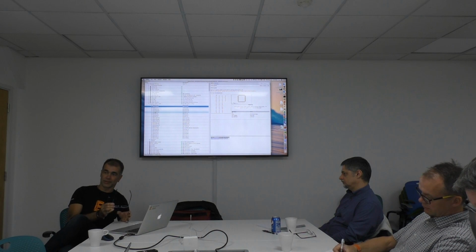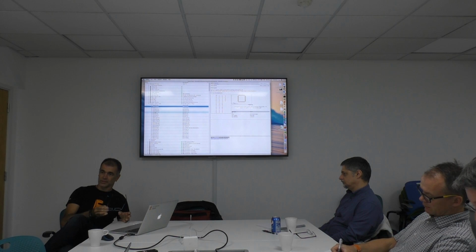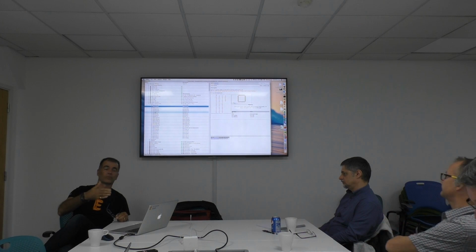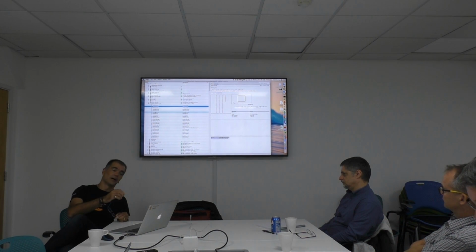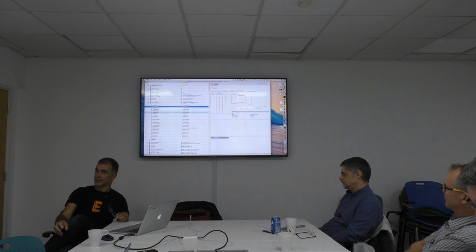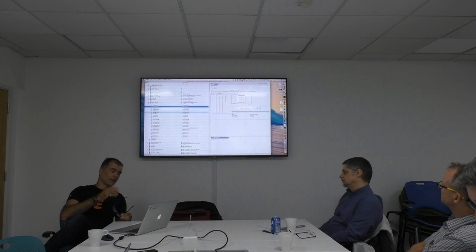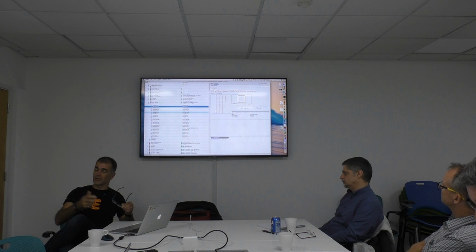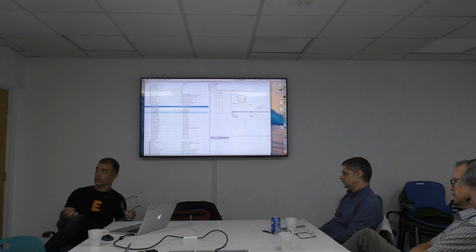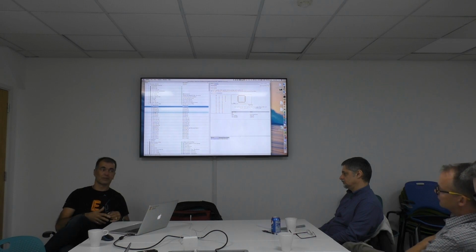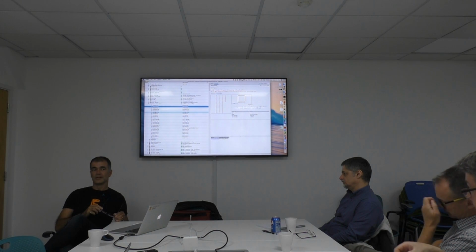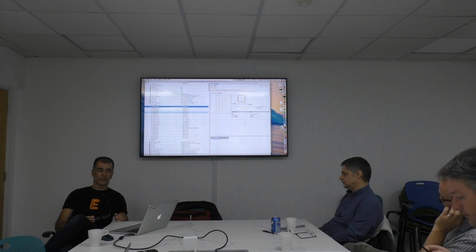You don't need it. But if you want to do some changes, you would like to add something, or you want to replace your components because you have a newer version of the component, because you decided, I don't want to have my name texts in this position, I want to have it anywhere else. Then it doesn't fit together. And then you have to delete and add, and the whole mechanism, library update, for example, does not work anymore. So that makes things not undoable, but more complicated. So that's one of the things you really have to take care of.